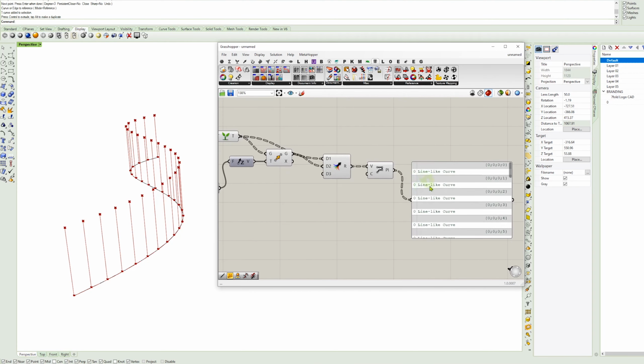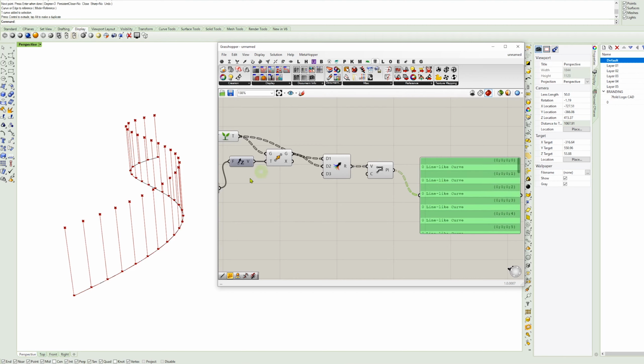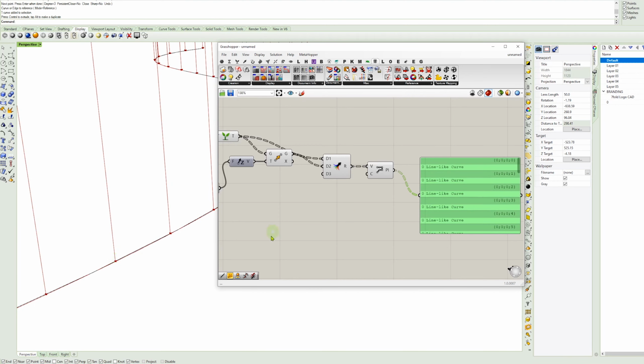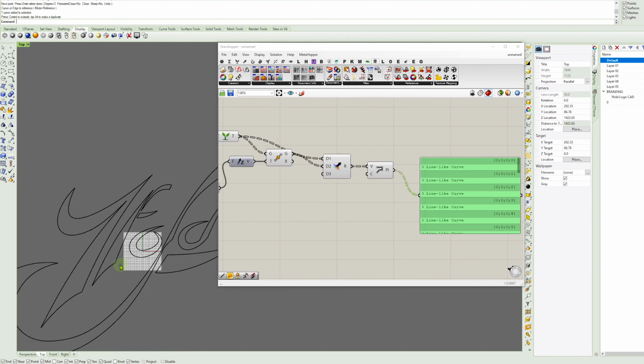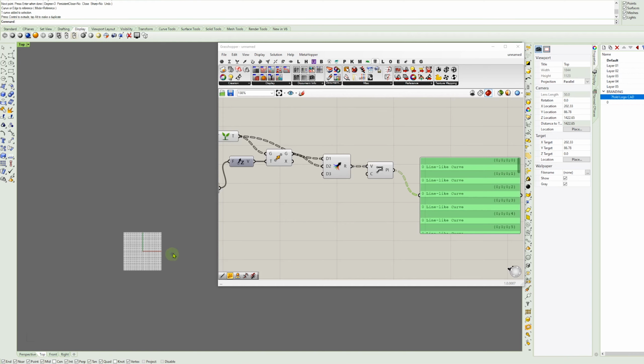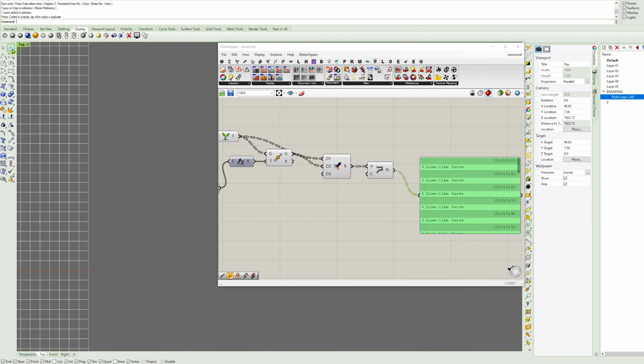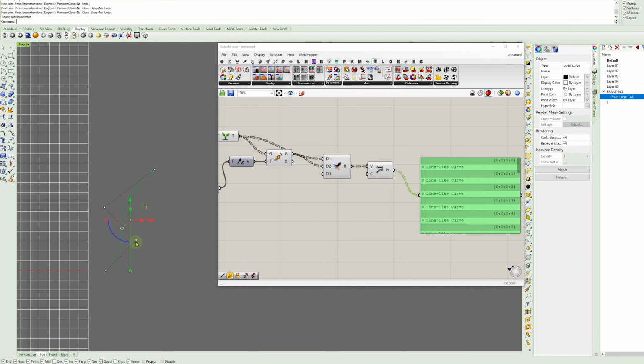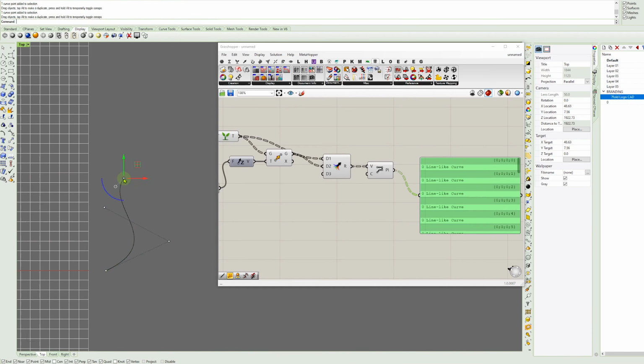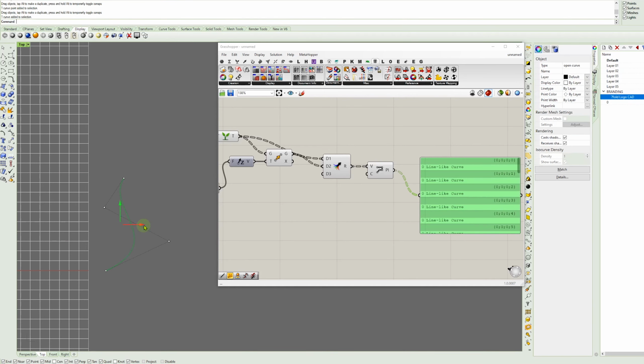And then what we're gonna do is we're gonna switch gears for 2 seconds and create our section profile that's gonna go on there. So if we go to a top view here, and let's just hide this guy, and let's zoom in to anywhere, and I'm just gonna grab a polyline, and actually let's make it fun. So I'm gonna do a spline again, and I'm just gonna make that kind of S shape I was doing before. Maybe edit this a little bit so it's a little bit more dynamic. And then I'm just gonna alt drag a copy.